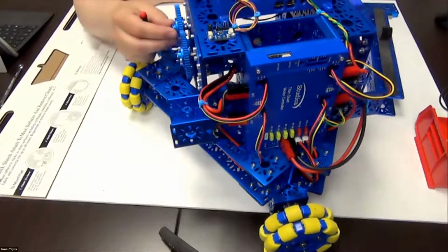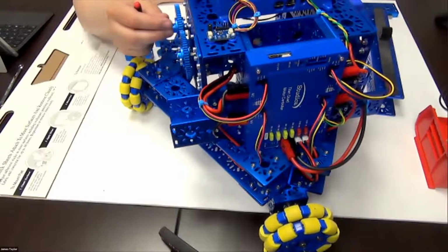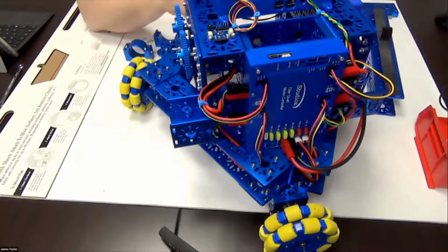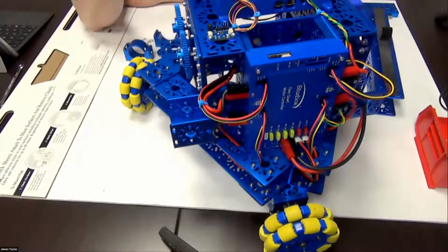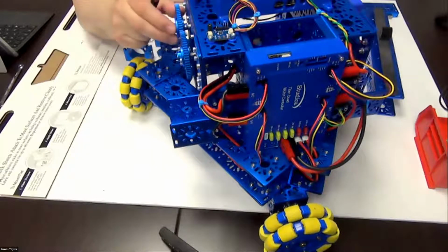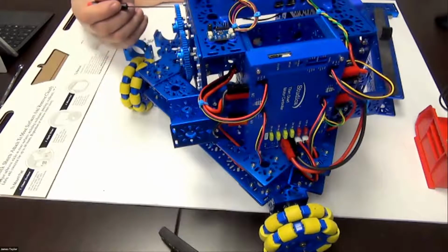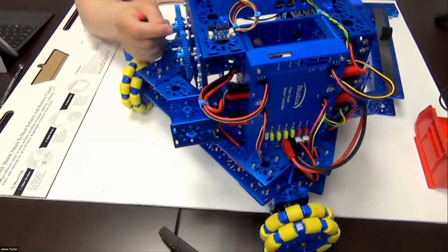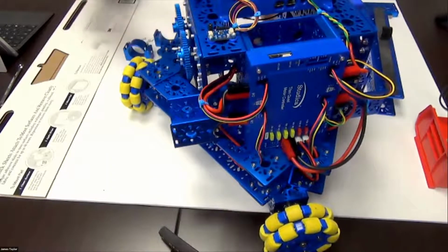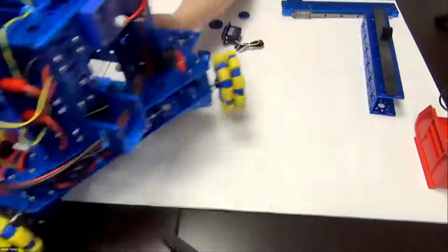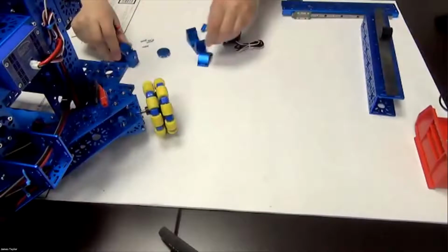Because this is a critical component, all right? It drives this mechanism with a DC motor, which is a fairly high torque motor at the 60-to-1 gear ratio that's on here, right? So we want to make sure that this does not slip or fail, so we have doubled up on the components here. And I'm just going to move our robot out of the way a little bit.